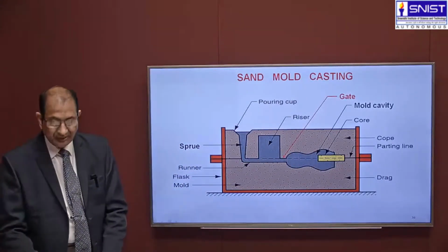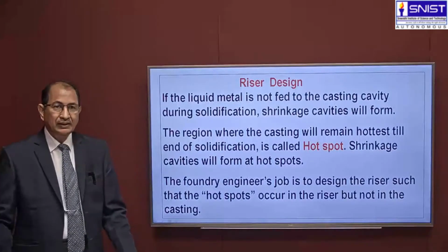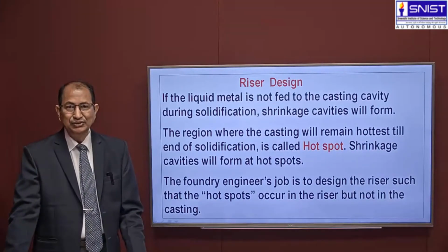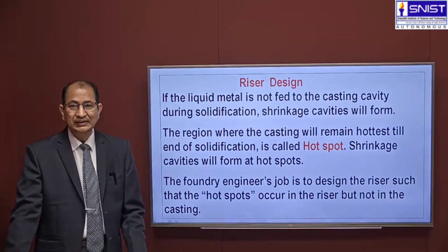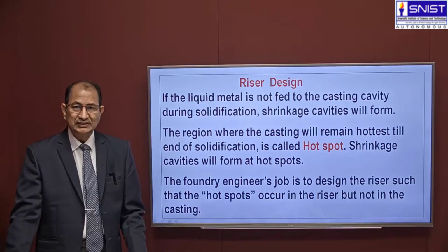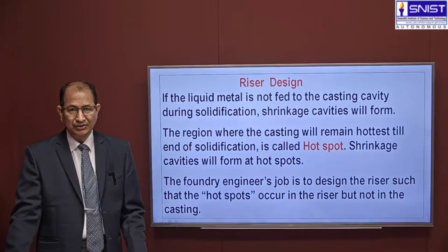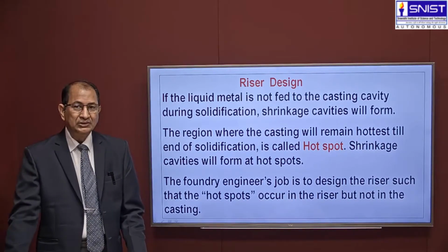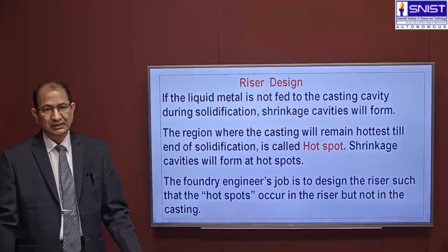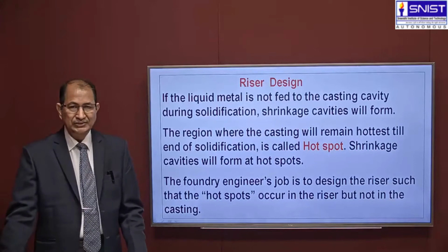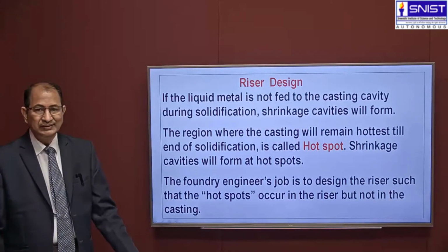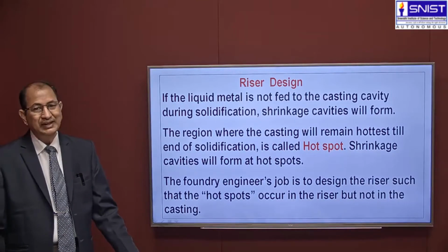Now, having said that, if the liquid metal is not fed to the casting cavity during solidification, shrinkage cavities will form. The region where the casting will remain hottest till the end of solidification is called the hot spot. Shrinkage cavities will form at the hot spot. The foundry engineer's job is to design the riser such that the hot spots occur in the riser but not in the casting.